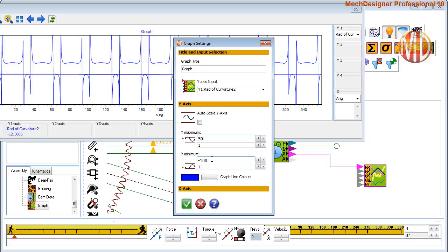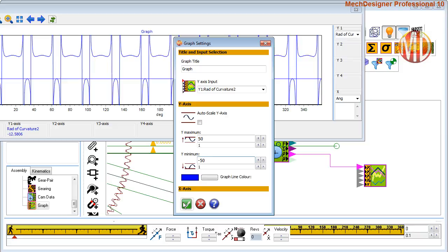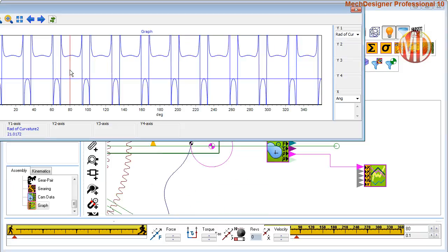So we've got a 10mm pin. It's probably not going to be much more than 30mm. So I'll put plus or minus 50 as a dimension. And then we can see these lobes here. So you can see the radius of curvature is 20, and in that direction 12.